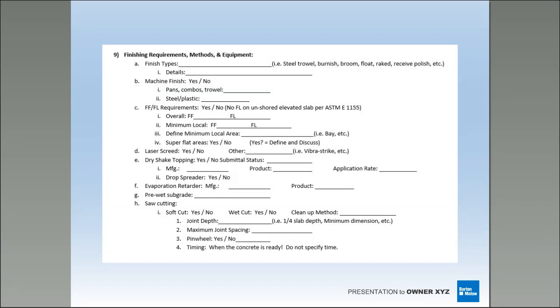And do a mock-up grind on it. I would not move forward until your place finish guy is comfortable with what he's pouring and the mix design he has chosen, and that you guys are comfortable with what you're polishing.